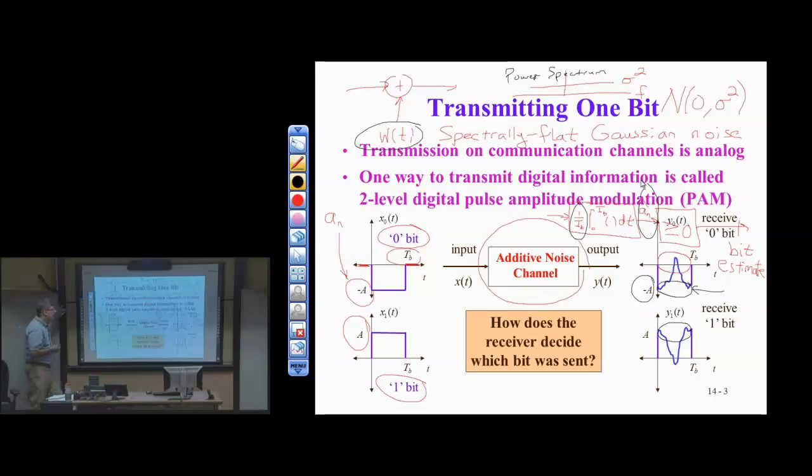Yeah, if you integrate over a finite period of time, you're fine. Remember, the integrator has trouble if you let it run over an infinite amount of time and you have a DC input, your output grows without bound. But over a finite period of time, yeah, this is a good way to estimate the DC value. Because what is this? This is really a DC value over the symbol period. So it's also on the midterm, where I asked about DC offset in communication systems, and this is a way to estimate what that DC offset is.